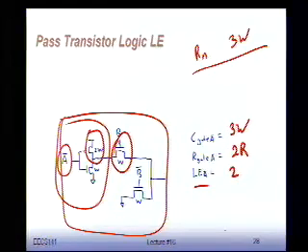So if you take that driving device into account, you say, hey, this ain't good. This is a gate that has logical effort worse than what an inverter would give me. It's not that bad, because it's actually implementing an AND gate, which has a logical effort of 4/3. But still, it's not something to be perfectly happy about.